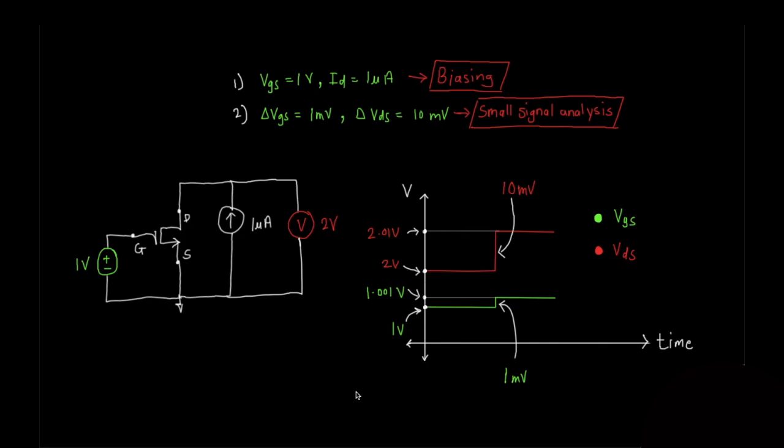If so, then after biasing, the circuit can be thought of in a totally different manner, like it gets all its small signal parameters at work. Let's call it a small signal model of the MOSFET. This model of the transistor will only include parameters which we call small signal parameters. Now, how can we model it? Well, let's follow the steps that we usually follow. After biasing, we generally start with nudging the input. So let's draw 3 points which indicate gate, drain and source. Now we are giving a nudge from an outside voltage source between the gate and source terminals.